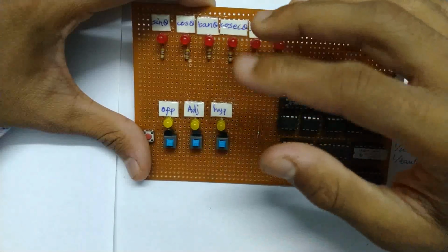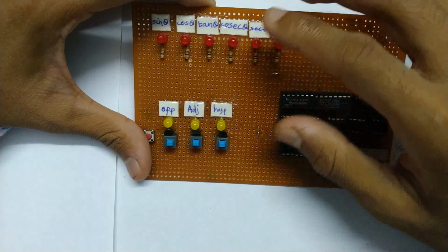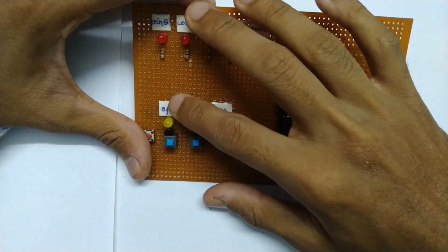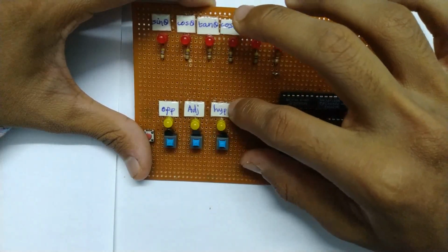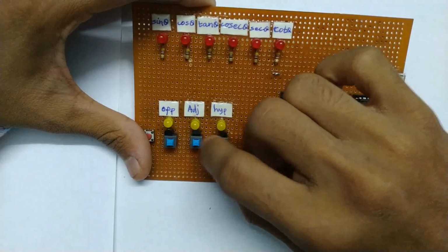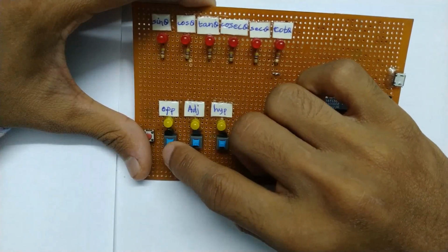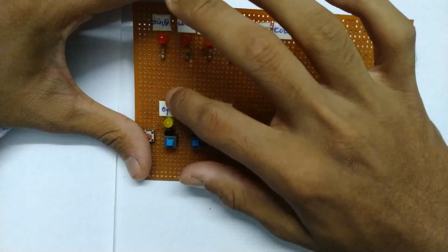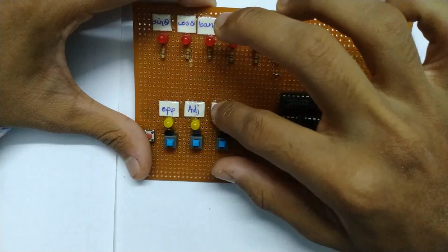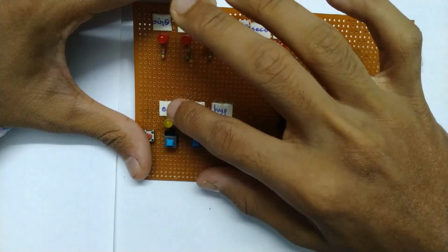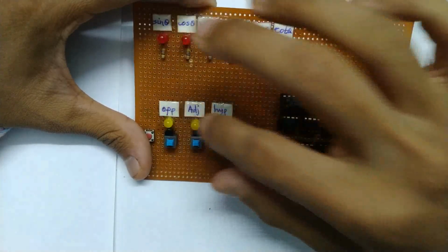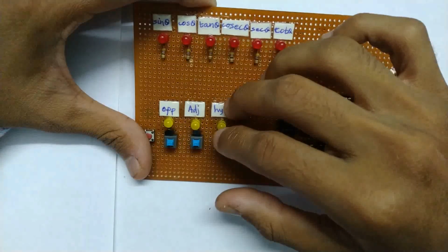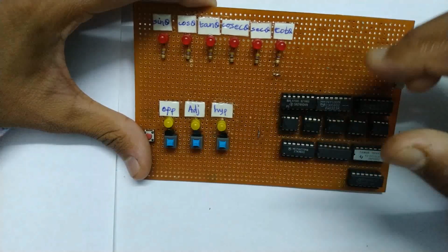So such kind of situations will obviously occur. So I had to redefine my problem statement wherein the output depends on the present as well as the previous input. So if I'm doing hypotenuse by opposite, that would mean that my present input, or the input at the moment, is opposite, but the previous input was hypotenuse. So my circuit will take the readings for opposite as well as hypotenuse. Basically, a circuit whose output depends on present as well as previous inputs is known as a sequential circuit. So I had to go through sequential logic.